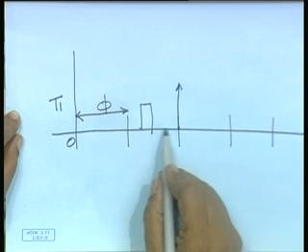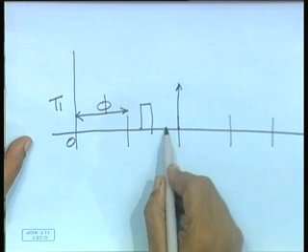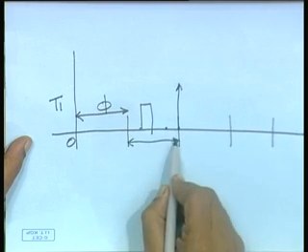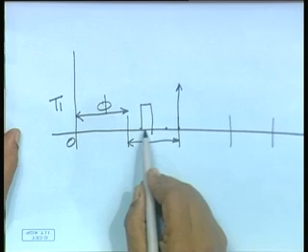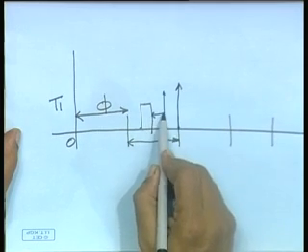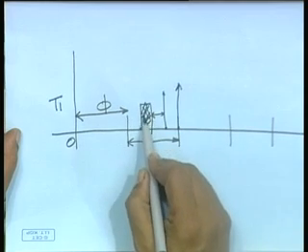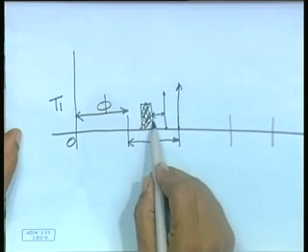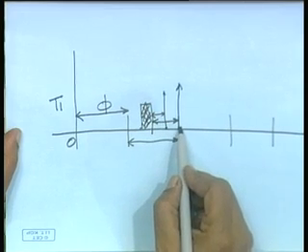It may be different, it may be that it has to complete within, let us say, 10 millisecond, and the period is let us say 50 millisecond. The task is repeating with a 50 millisecond frame, cycle, but the deadline is 10 millisecond from here. It is possible, but typically we will see that all tasks that we normally come across will have the deadline same as the start of the next task.